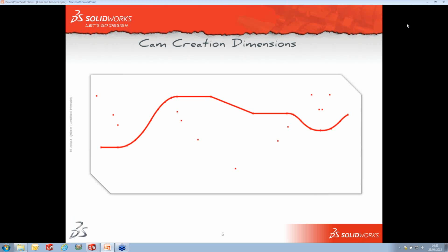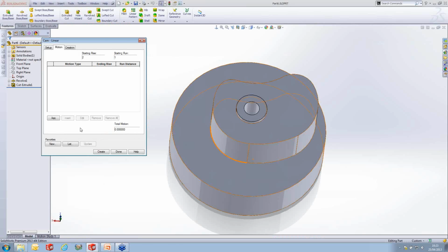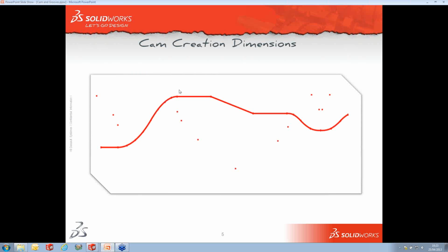So just switch back to SolidWorks now. So the first part of movement I want to put in, if you saw that little picture, we had a dwell, and that dwell just took us over a small value of 2 millimeters. I'm keeping this item fairly small, and then we're going to rise up that steep path there up to about here.